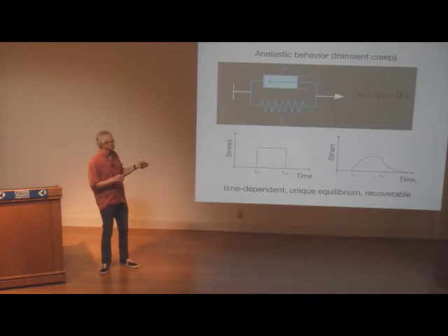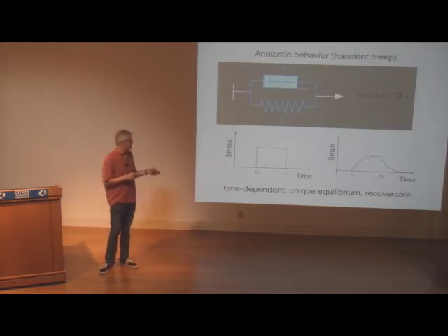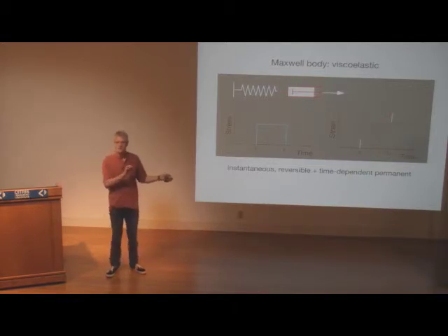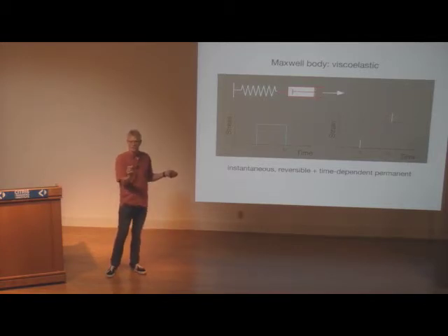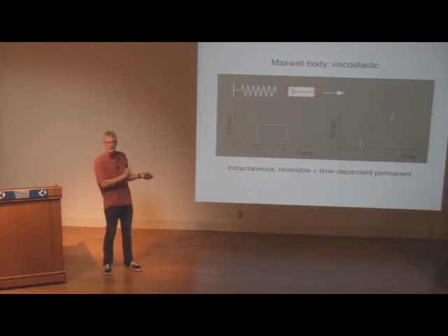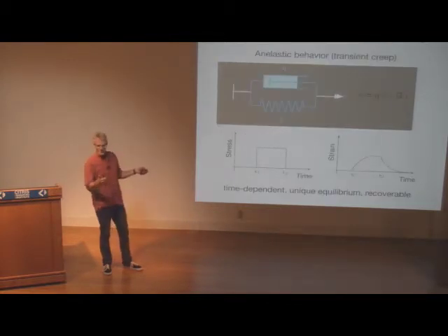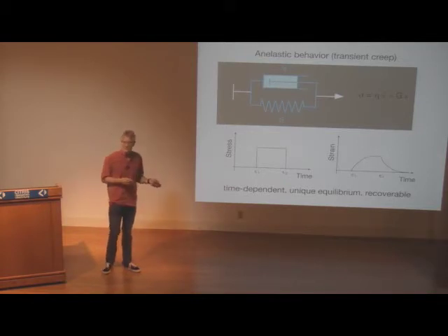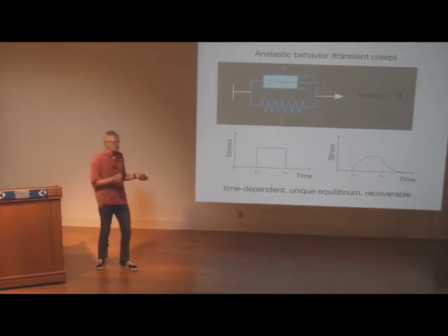On the other hand, if you just had the dashpot like in the Maxwell model, you can, of course, have an infinite dashpot and can do infinite deformation, right? There's no restoring force. The spring, from Hooke's law, we know that there's a proportionality between how much deformation you get and what the applied stress is. For a very small stress for a dashpot, you can just keep going. Here, for one, it's not instantaneous, but two, you have a finite strain, right? At some point, the spring will balance the applied force.